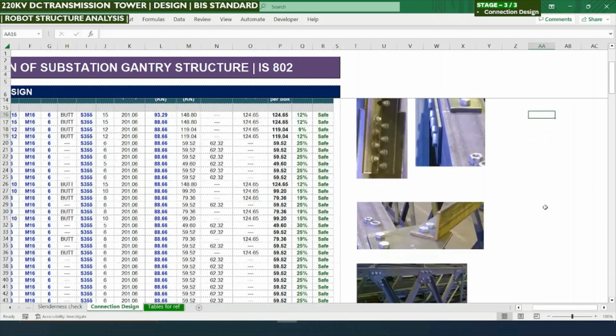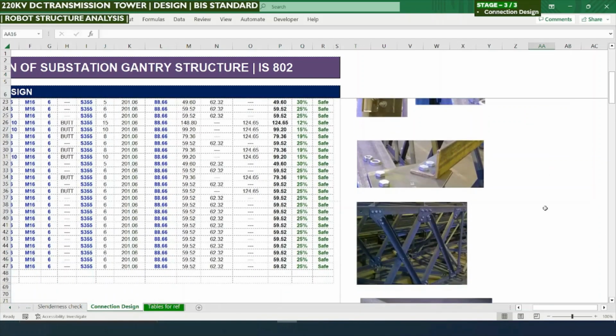Next we can look into the bracing bolts. This kind of bracing has 2 bolts in the connection. If the 2 bolts cannot be accommodated on the main leg member, because the flange is too small to accommodate the 2 bolts from the bracing, we need to provide a flat plate called a gusset plate.